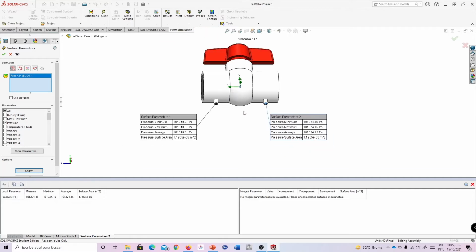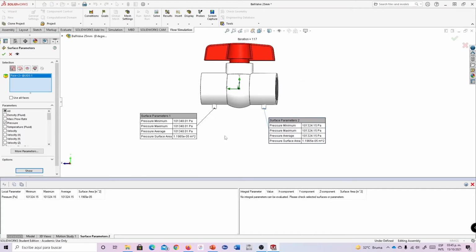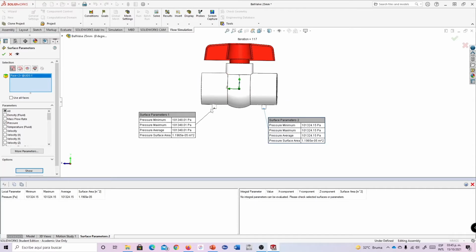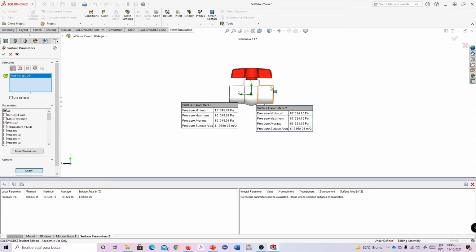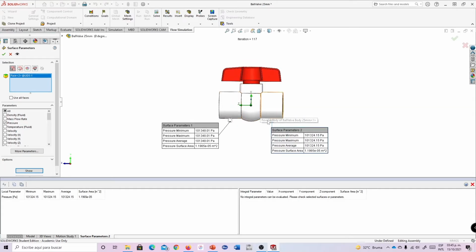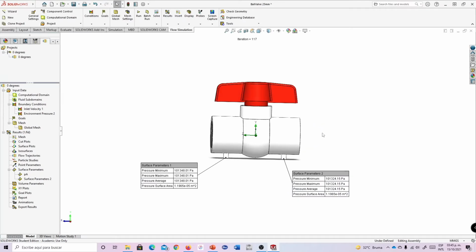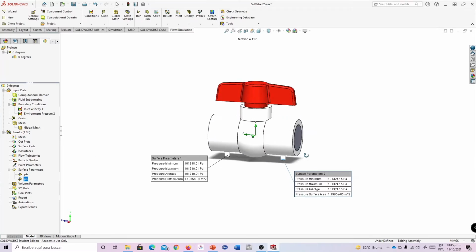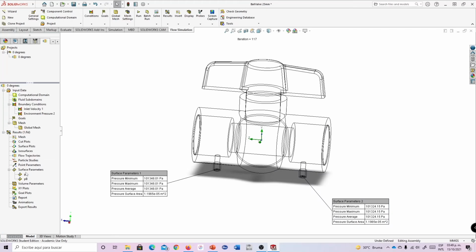Okay, here we have two different values for the pressures of the different sensors, sensor A and sensor B. So for our calculations, we're going to retrieve these values and calculate the pressure drop past this valve. So I'm going to change the name here to pressure B.